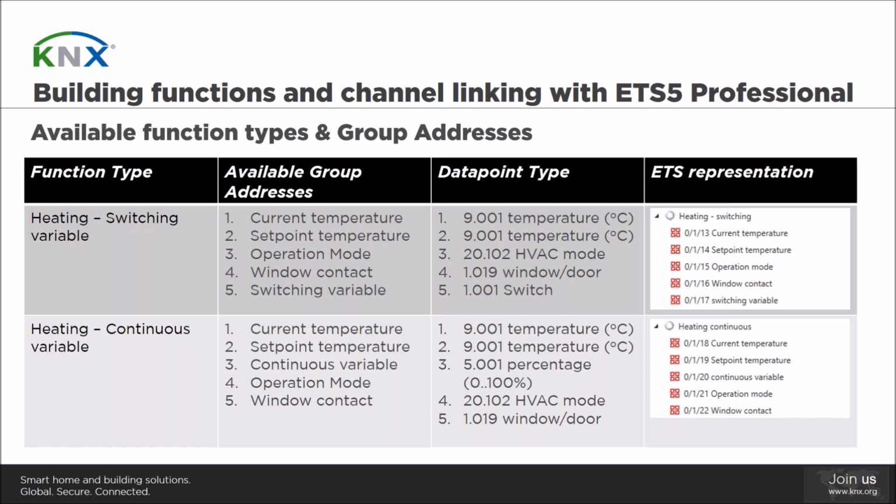If you use those standardized functions provided by ETS, it will be much easier to expose your installation's information to an internet call via the KNX IoT interface, since ETS will be able to interpret the meaning of the functions in your project, facilitating the export of the project information to the respective KNX IoT interface.